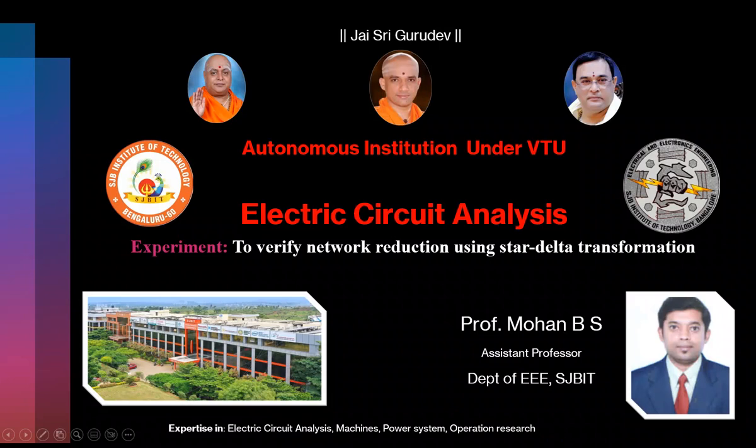In this video, we'll be verifying network reduction using star delta transformation. We'll see theoretical calculations, some basic concepts, and how we solve this on hardware.